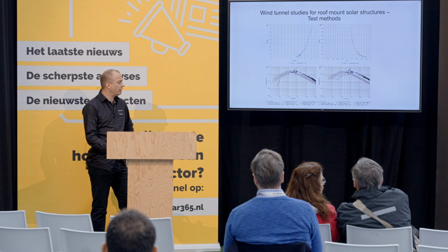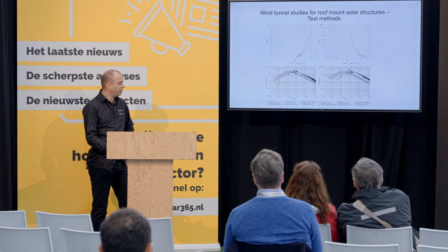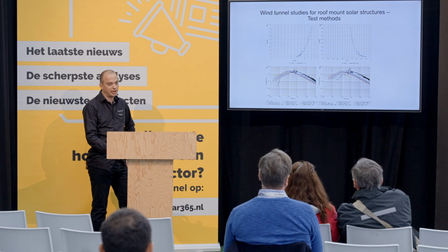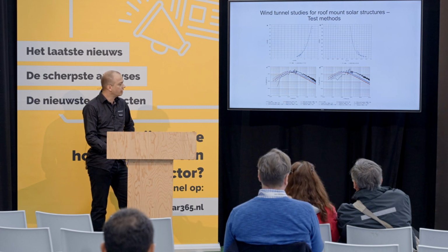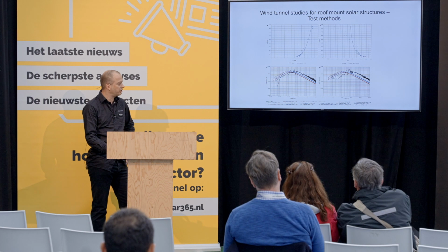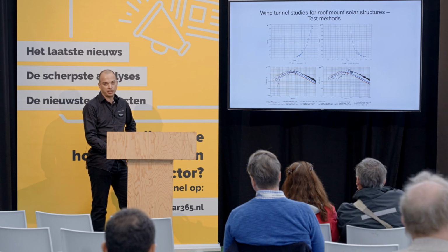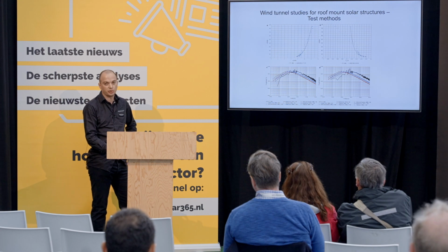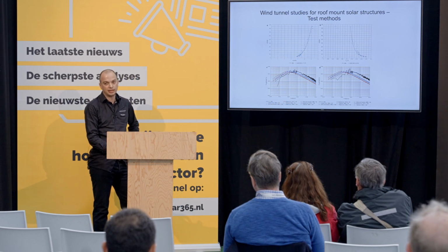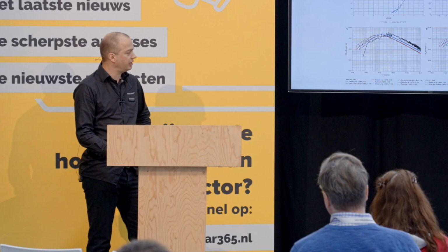These diagrams are actually very important. The black lines show the measured data in the wind tunnel, and the colored ones are full-scale data by several researchers, adapted to different geometric scales. One can see that on the right of the diagram, there's an overshoot of turbulent energy, which is safe at high frequencies. And in the low frequency range, there's an underprediction. That needs to be taken into account in the analysis of pressure coefficients, and it's a common mistake that I've seen a lot in the real world that this is not accounted for.